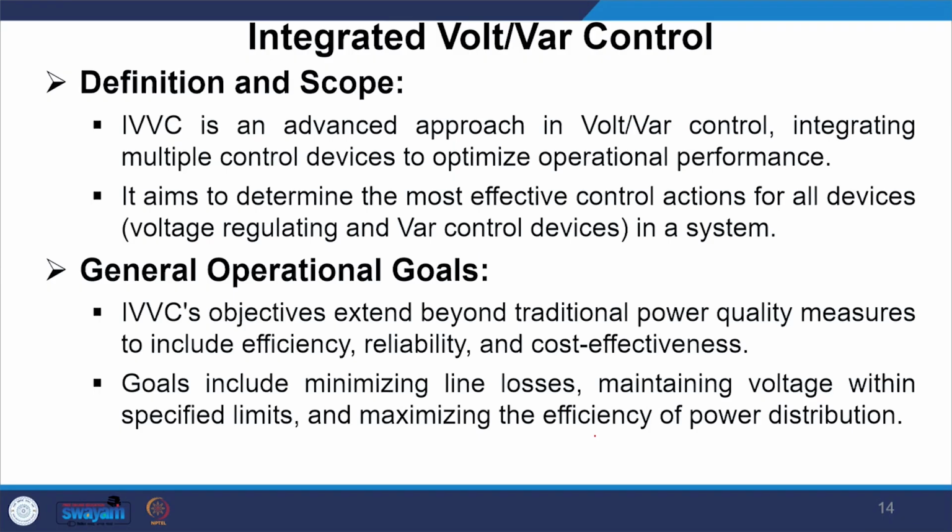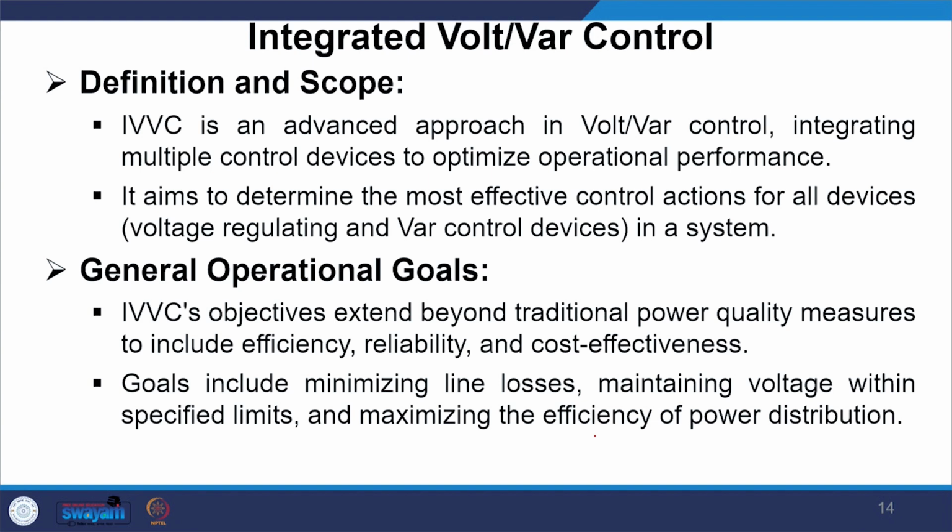Integrated volt-var control, with the acronym IVVC, is an advanced approach in volt-var control, integrating multiple control devices to optimize operational performance. It aims to determine the most effective control actions for all devices, voltage regulating and VAR control devices in a system.